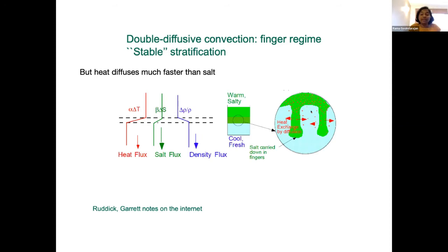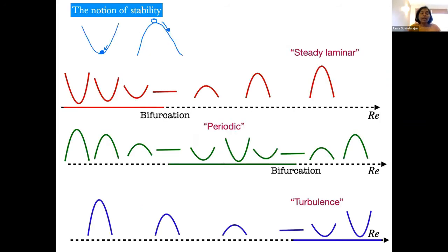So that makes it go down more, and then this going down will become exponentially faster and faster because it is giving up heat fast and retaining salt. This is the basic idea behind one kind of double diffusive convection. You can do the opposite and then also you'll get an instability, and you can read up about it from Turner's book or somewhere and work it out for yourself. It's a fun thing. Okay, so what is our notion of stability?